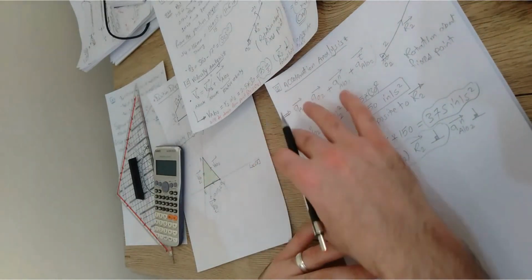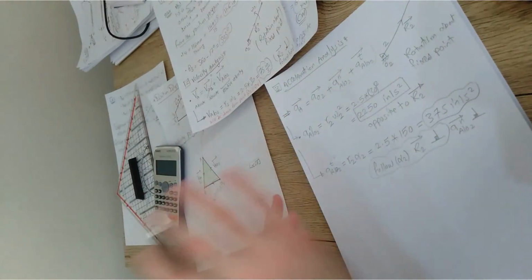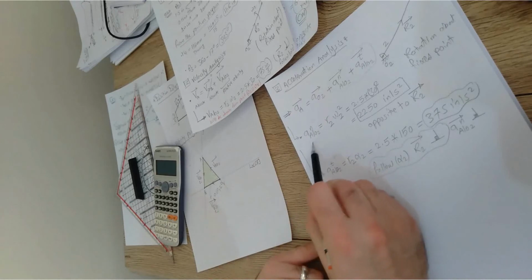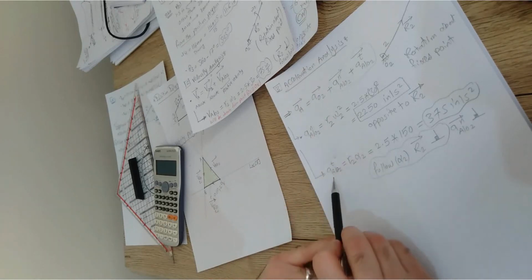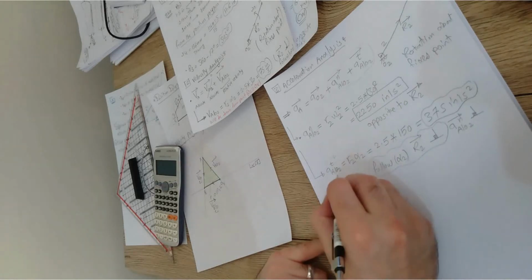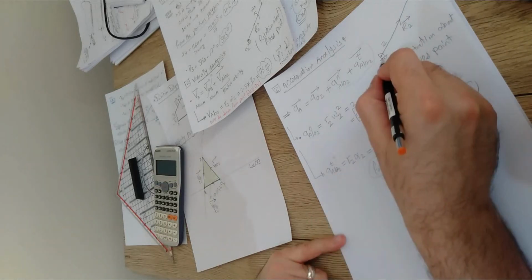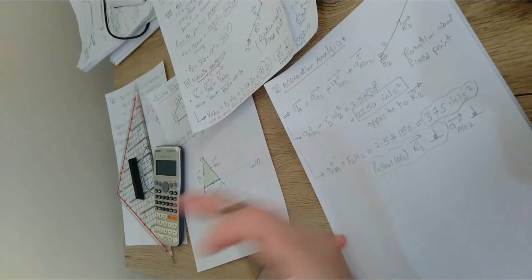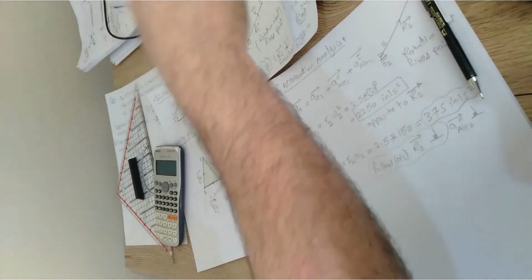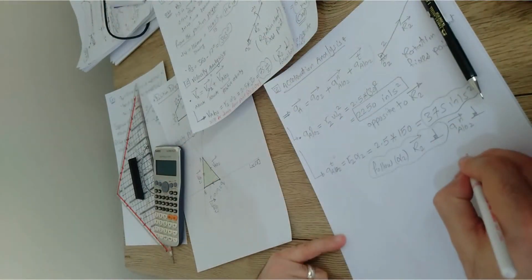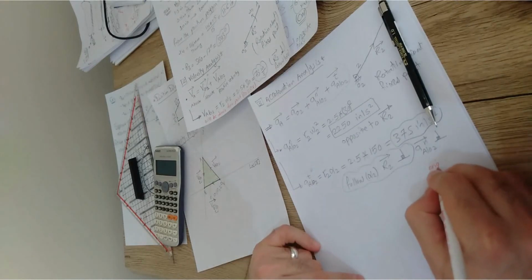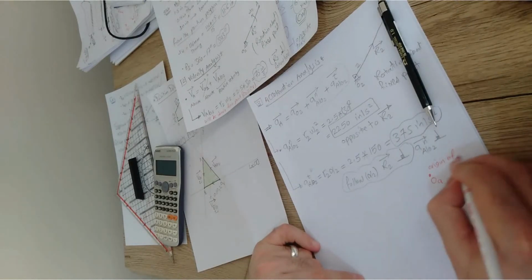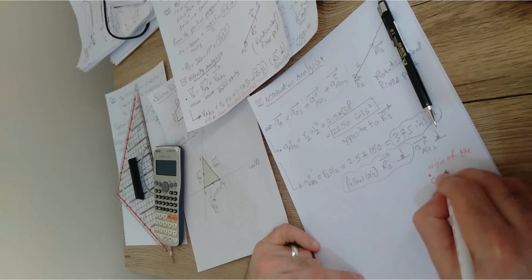So these are the two components that shall be drawn. How can you draw them? These two components should be drawn from either point A or point O2. Since O2 is a fixed point, its acceleration will be 0. And again, as we did for the velocity, we are going to define OA, which is the origin of the acceleration polygon.